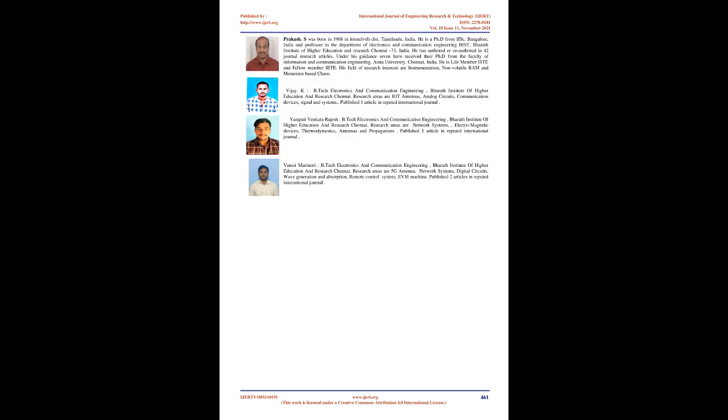Figure 9, simulation result of the non-inverting amplifier. Figure 9 shows the output of the non-inverting amplifier. When an input voltage is applied through the non-inverting terminal of the op-amp, the two memristors provide a voltage divider in the circuit. Hence, the input voltage is applied to the positive terminal of the op-amp, and the output terminal is fed back to the negative terminal of the op-amp through a resistive divider formed by M1 and M2, figure 3, so the output has the same phase as the applied input voltage.